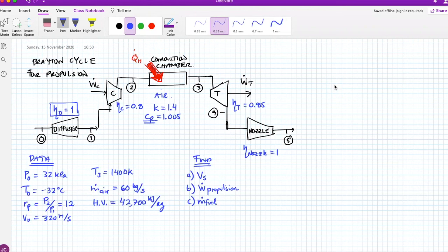In this case, we're gonna look for a Brayton cycle that has more machines because it's intended for another thing. Its purpose is propulsion. So the basic idea is to accelerate an incoming flow of air. These things are mounted below the wings of planes, and it's one way to propel vehicles through air, for example. So these Brayton cycles are meant for propulsion. In that case, we will have certain differences with our typical Brayton cycle for production of electricity.